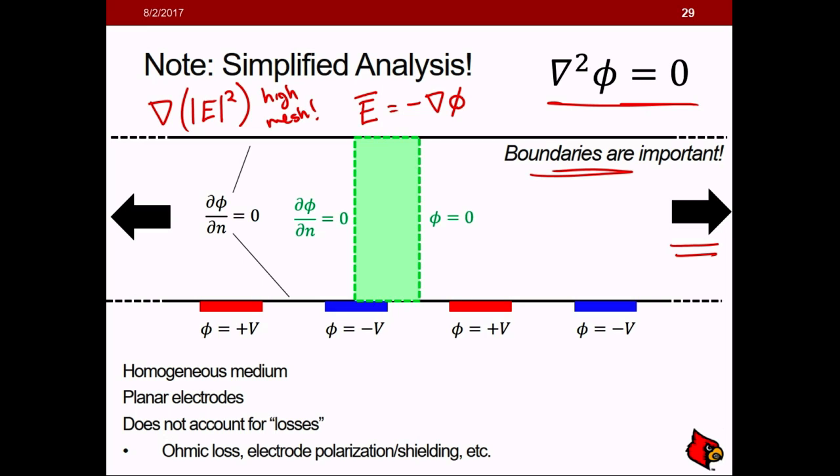The potential between two neighboring electrodes would be 0. Then you have a mirrored symmetry above the center of the electrode. So you can take this whole system, and if you want to look at its behavior, you can just take this little sliver, analyze that, and get what you can from that. So in the end, look for symmetry within your system, because you will likely need a fine mesh, even in 2 dimensions, to accurately model dielectrophoresis.